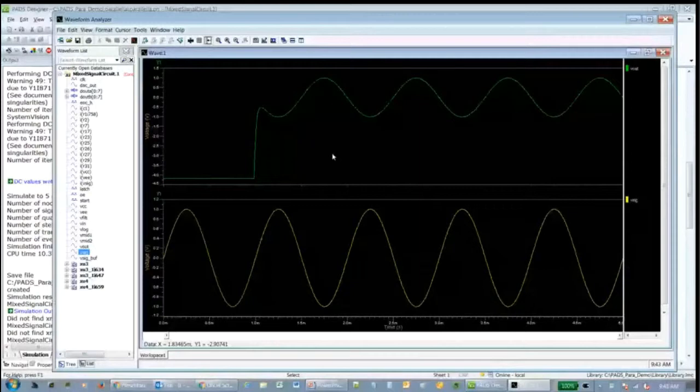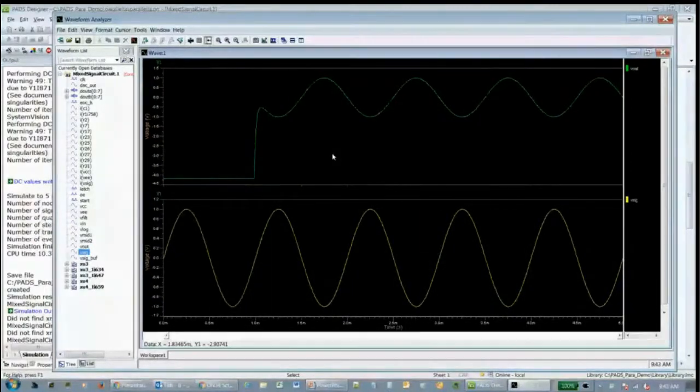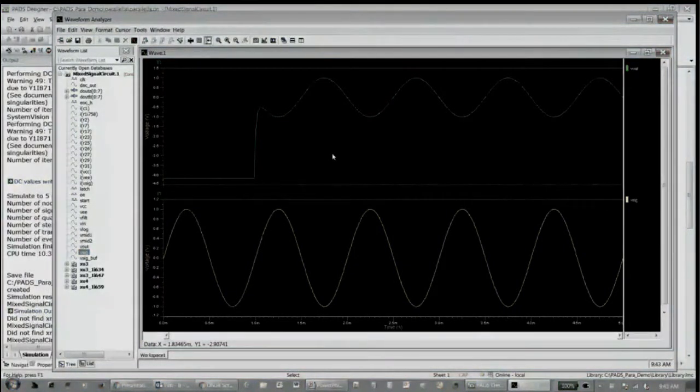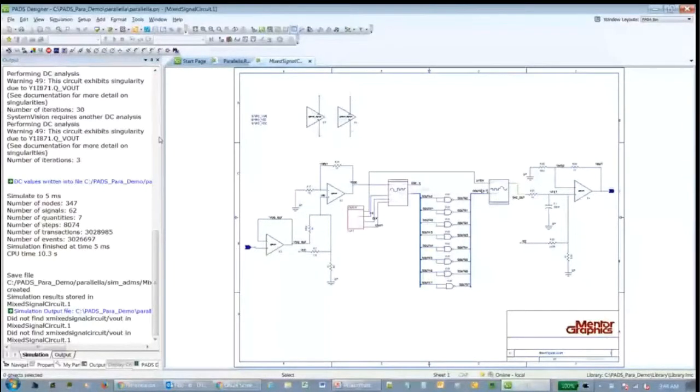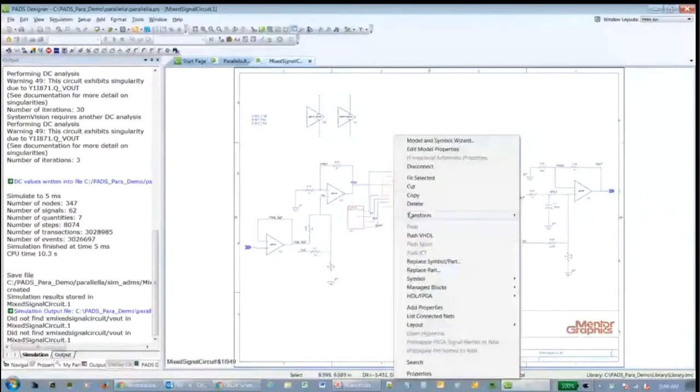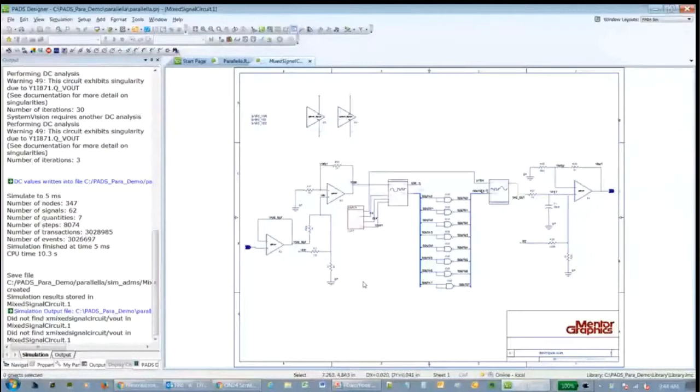I just wanted to show you that you can work in a fully integrated environment in your schematic and take this data right into PCB without having to do a lot of modifications for the purpose of the analog simulation part. And we can do advanced things like the VHDL analog simulation functions.